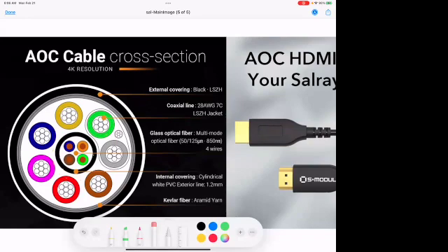So all of these designs have been made possible because we started with the fundamentals, and eventually, the way it's done, it looks very complex. But if you think that all of them are shielded and grounded, the shields, all of these shields, the green, here, the green shield, the yellow, the blue, the pink, all of those are grounded. The moment they are grounded, they are totally isolated. Okay, and then you can design them independently. And then you just place them all together.